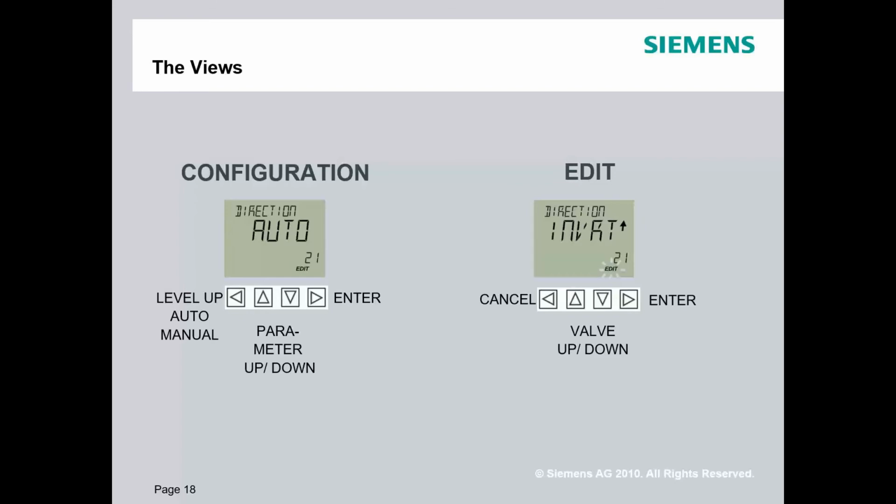One other question. Is there a recommendation for what level of plant air filtration is recommended for either the PS2 or the PS100? Everybody in the positioner business goes by a certificate, and I can get you the little paper. But what the PS100 and our flagship PS2 have is, where the air goes in, there are little screens that are about 5 micron. And I will be 100% honest with you right now. If the digital positioner, anybody's, not just mine, has a weakness, it's air. I like clean air. Everybody in the digital world likes clean air.